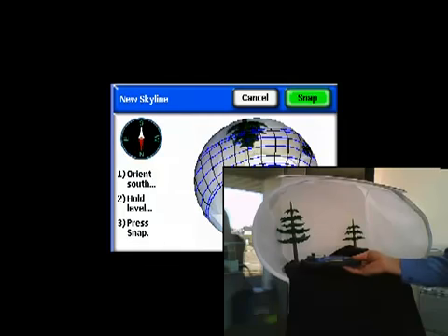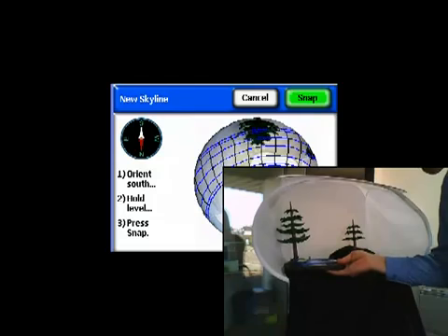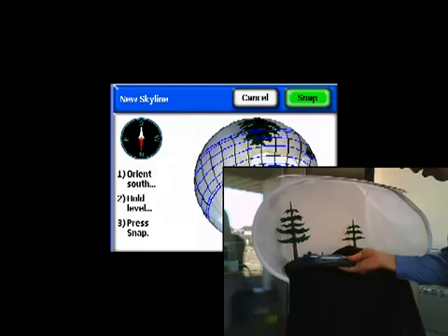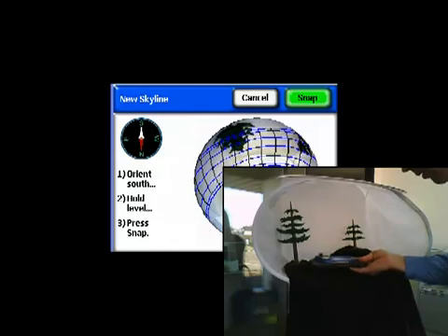Let's look at the preview mode in more detail here. We're holding the SunEye south and level, and we can walk around to different locations on the roof. Let's begin down on the low portion of the roof. Over on the east side, we can see the effect of the larger tree, and a little bit from the other tree to the west. Now let's walk along the roof toward that smaller tree. We can see it start to come into play there.